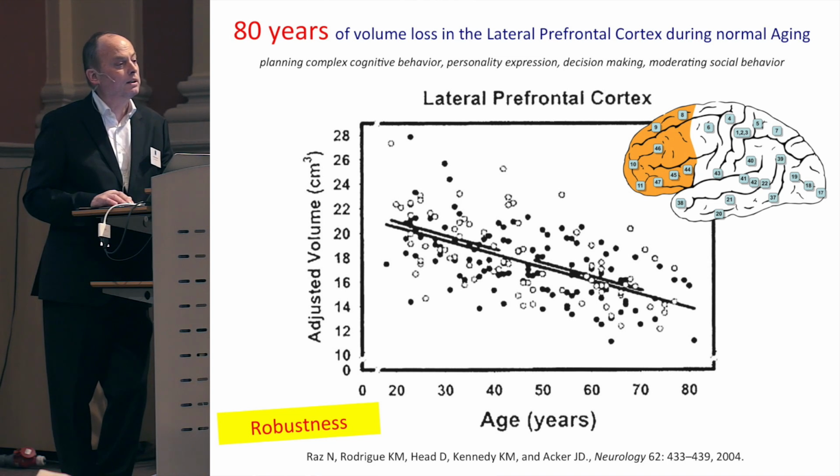So the robustness of these systems is quite interesting, and we all fundamentally understand why that is. It's the fact that information is distributed in the system, and it's a massively parallel structure, so if you remove part of it, the system still works. It has what we call graceful degradation. And that is a very interesting feature also for artificial computing systems, because it's increasingly difficult to make all transistors work. So to be able to work with non-functioning transistors on the level of 10-20% would be extremely important for the use, for example, of very deep submicron or nanoelectronic devices.